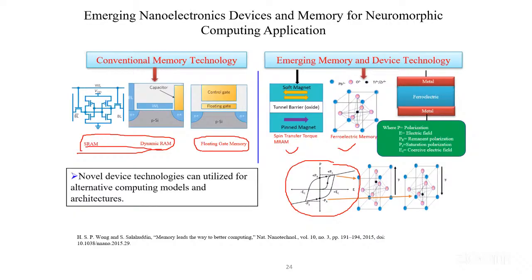Because you have hafnium oxide doped with zirconium ions, and this zirconium ion can be placed above the center or below the center. And the dipole moment of this complex molecule will depend upon the symmetry, or the presence of this black zirconium ion, which makes it ferroelectric in nature.